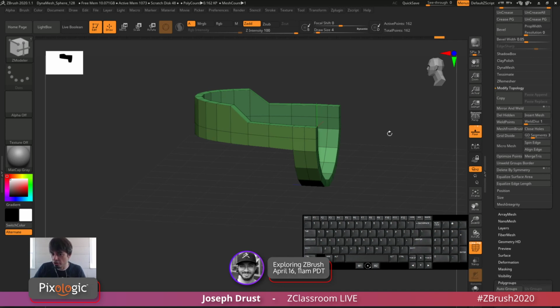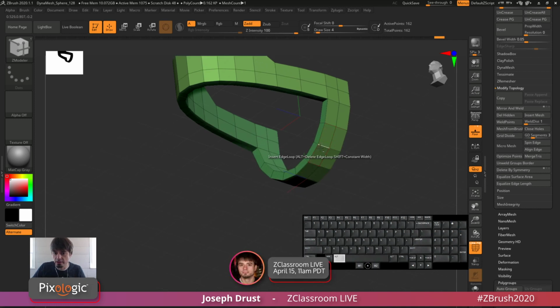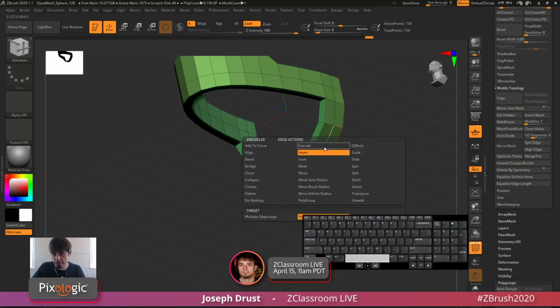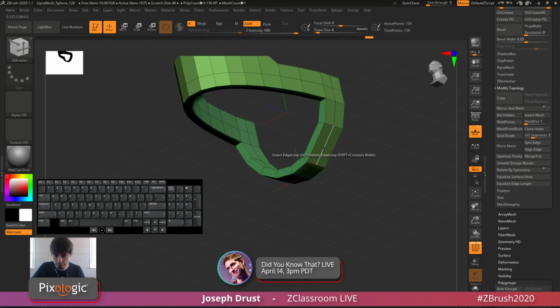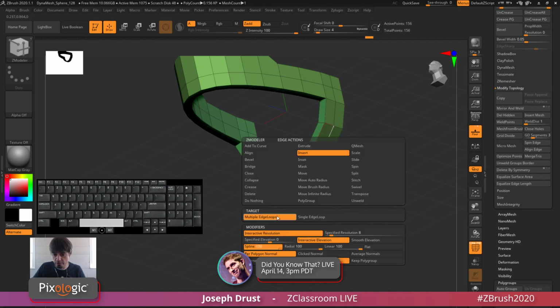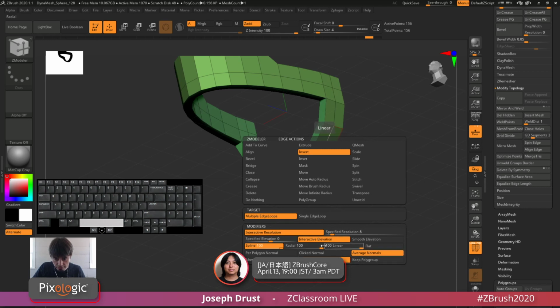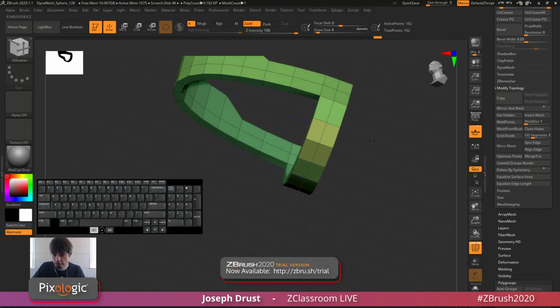Pedro's asking about curvature and adding an edge loop. So if I come through here and say remove this edge loop here, and I want to add this back and give curvature to it, basically in here, move my keyboard. If you go to the insert option, multiple edge loops, there is an average normals right here, and this should do what I'm looking for. Where's it at? Maybe it's smooth elevation. There you go. Smooth elevation.